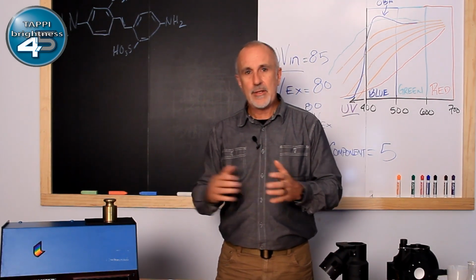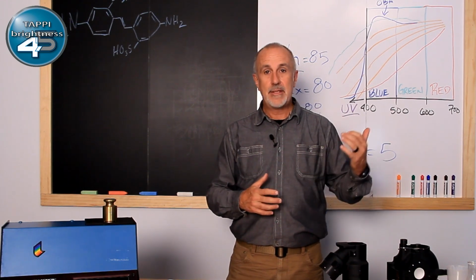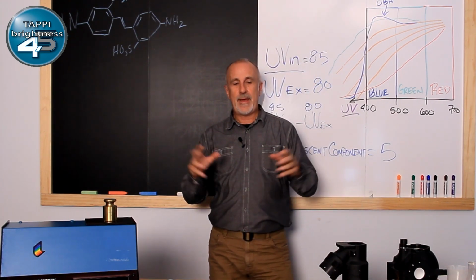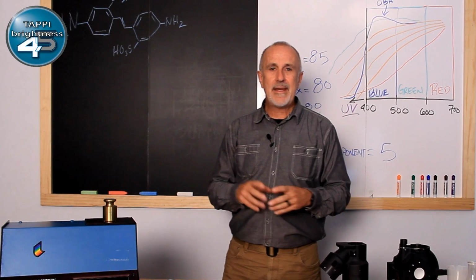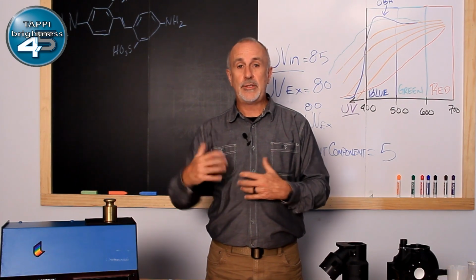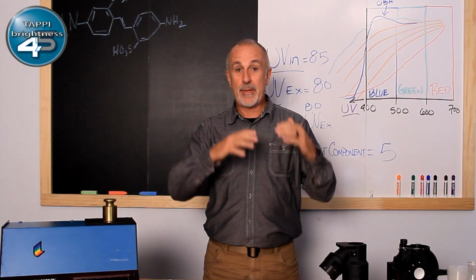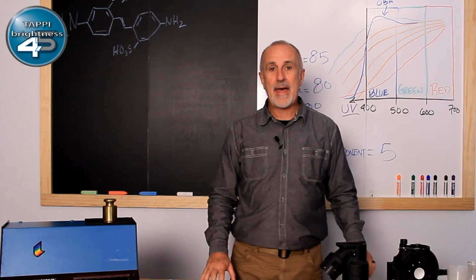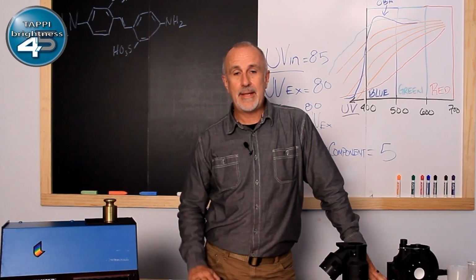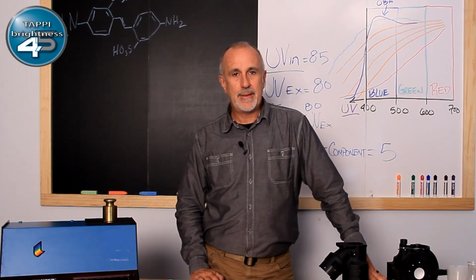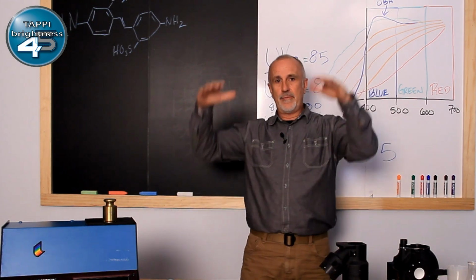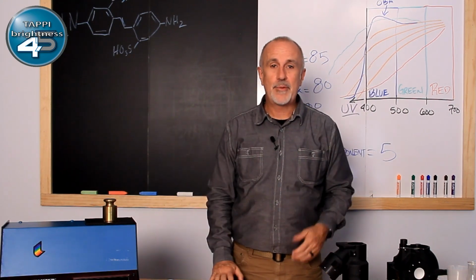So they did a study, and sure enough, the outcome of that study said this is certainly an adequate UV energy level for us to define TAPPI brightness around. They didn't necessarily look at it the same way ISO did, but they looked at this ratio of blue to UV energy. And if we could get that set properly and maintain that, then that would in fact allow us to establish a good point for calibration and be able to maintain that over time. So they wrote that into the standards, and then today in our calibration laboratory we maintain that point to make sure that we're not drifting all over the place with the addition of optical brighteners.